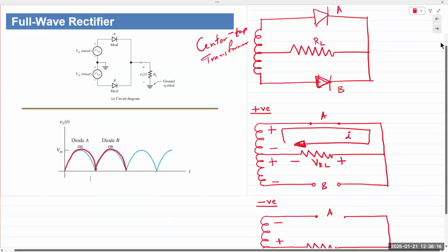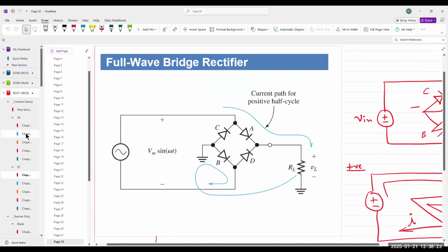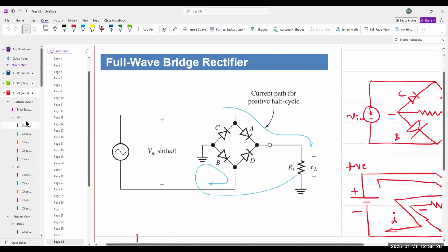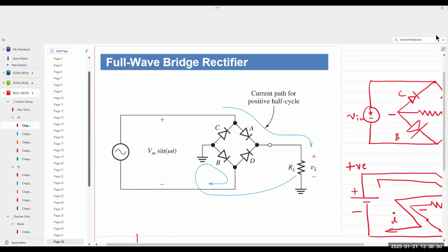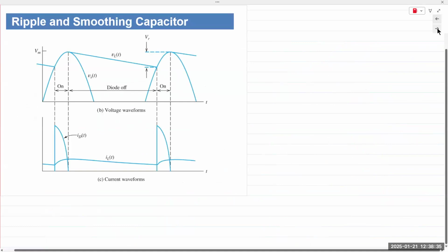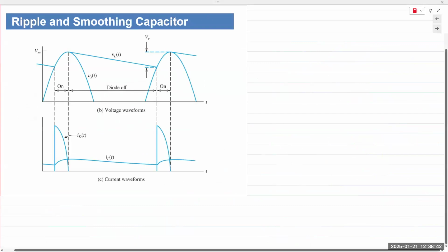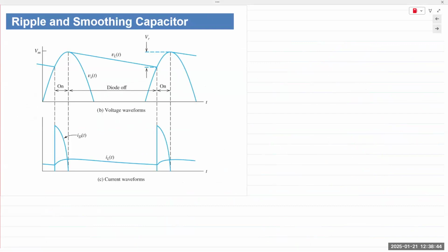All right, full wave rectifier, half wave rectifier. And we saw how the output of full wave rectifier circuits is still not a flat line similar to what we would expect for a DC. So what we need to do is filter out or flatten out the half peaks that we see in our output. And we do that by adding a capacitor at the end of our rectifier circuits, meaning before it gets to the load.